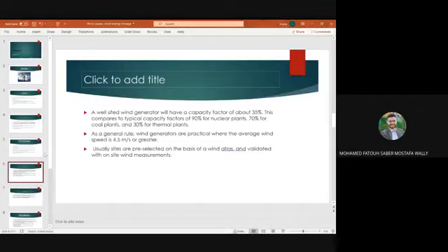In general, for wind power, we can take power from a turbine when the average speed is 4.5 meters per second. And if we construct a wind turbine in some place, we should use a place with constant wind speed.